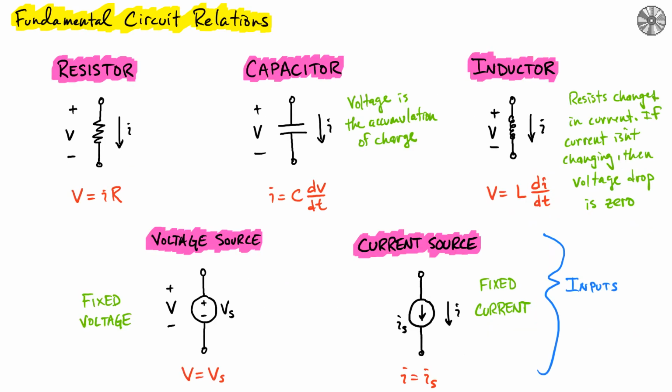The last pieces of information that you'll need in order to write differential equations for simple electric circuits are the fundamental relationships between voltage and current for each of the fundamental circuit elements. So in what we'll consider in this class, we'll talk about resistors, capacitors, and inductors. Resistors use a static relationship between voltage and current. And so if a circuit is entirely made out of resistors, then there is no differential equation element, simply because there's no change in either of those states with time.